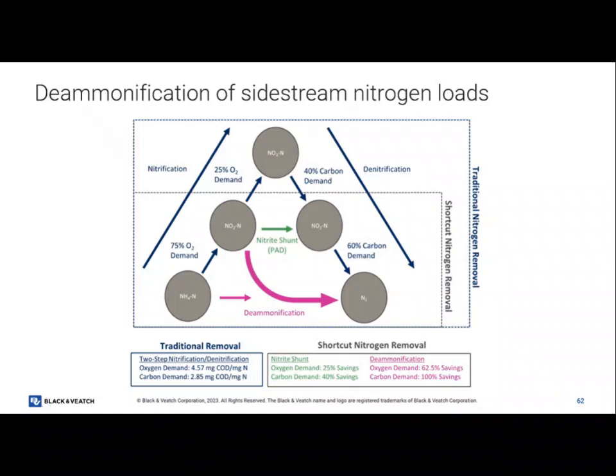If you don't measure nitrite, because nobody needs to measure nitrite every day. You should not be measuring nitrite every day for process performance. If you see a chlorine demand spike, go measure nitrite. Because it could be your chlorine went up because you have nitrite. Nitrite went up because maybe something's wrong. It could be that you turned your DO down. Maybe you were normally operating at a 3 DO and you turned it down to 1.5 DO, and that's too low. You didn't give them time to acclimate. And it could be an inhibition event. There could be a lot of things.